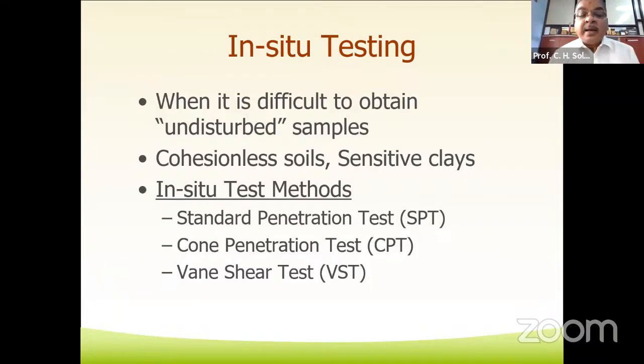Now we are coming to in situ testing. When it is difficult to obtain undisturbed samples, in cohesionless soils as well as sensitive clays, we mostly go for in situ test methods, and we have to rely on their results. Generally, in the case of cohesionless soil, the results obtained from the standard penetration test are interpreted for the foundation design.